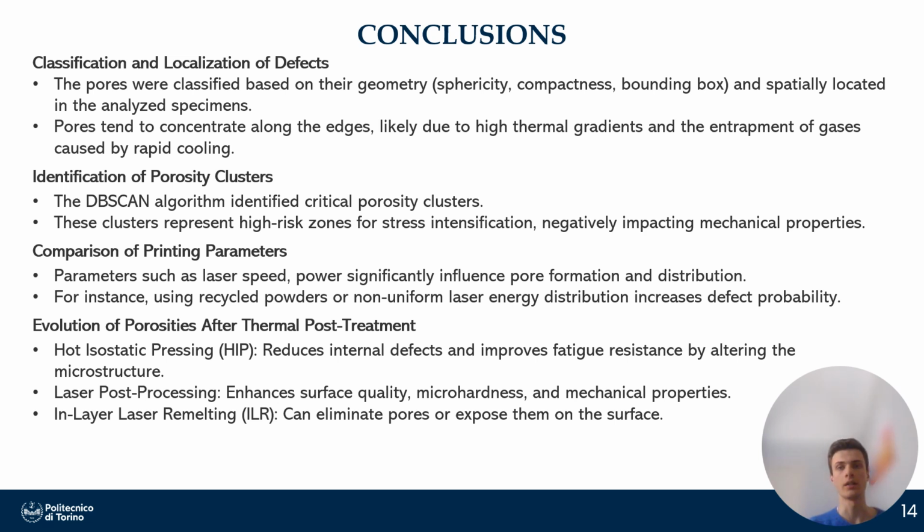We observed that they tend to concentrate along the edge, likely due to high thermal gradients and gas entrapment caused by rapid cooling. Furthermore, by leveraging the DBSCAN algorithm, we identified clusters of porosity, which are particularly critical as they represent a gray zone for stress intensification, ultimately compromising the mechanical properties of the material. This insight enables us to compare various thermal porosity treatment techniques to determine which provide the most beneficial effect.